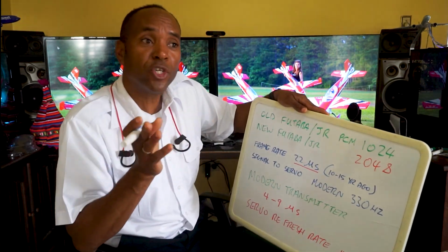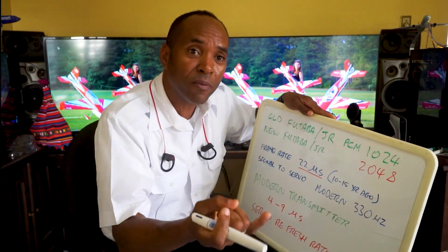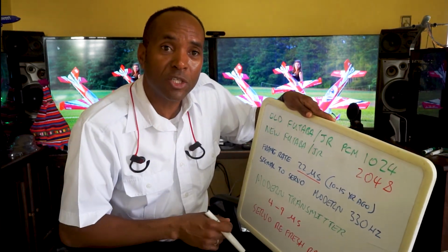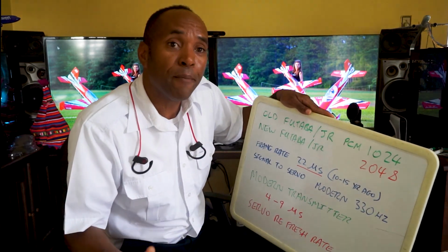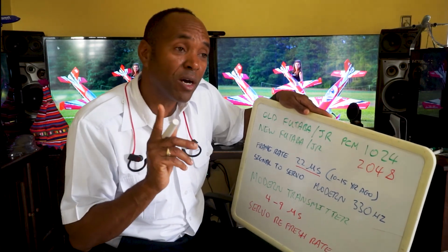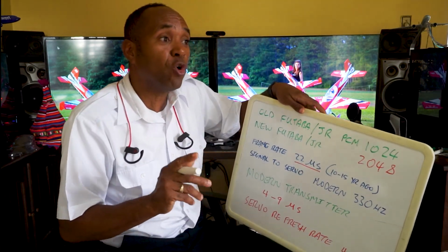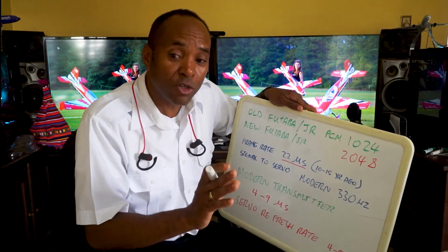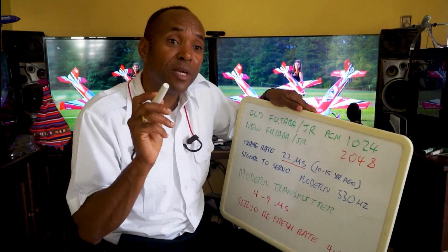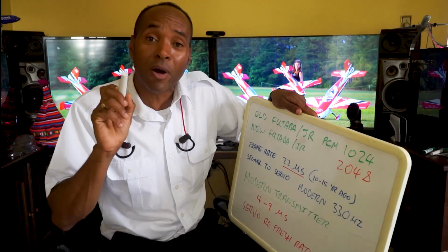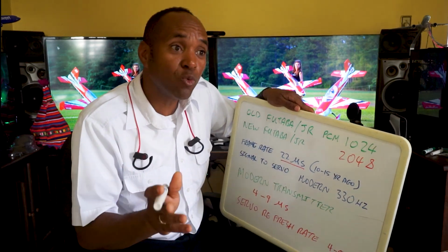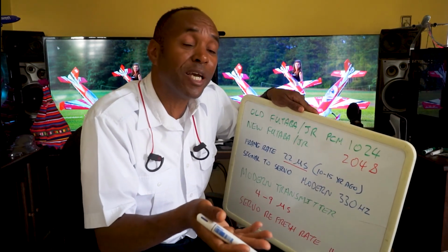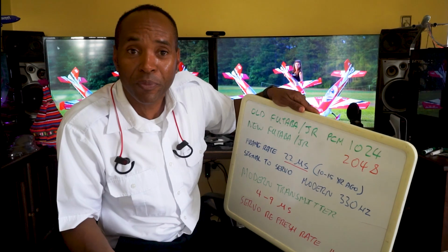We tend to shop for servos based on just the basic specs: how much torque, how much voltage, what kind of servo speed. But that is not enough, because the servos nowadays are so good. The servos themselves can be programmable, not just from a servo programmer, but through a modern transmitter, as well as the servo can be S-bus and F-bus capable, right?